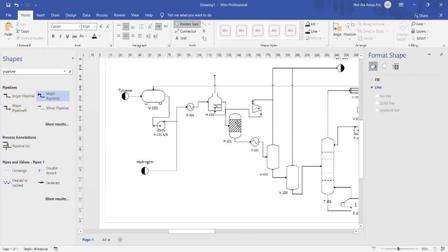We know that in the reactor, temperature has a significant effect, so we should control the temperature in the reactor to ensure that we can achieve the maximum conversion, which eventually leads to a higher yield produced from the reaction.